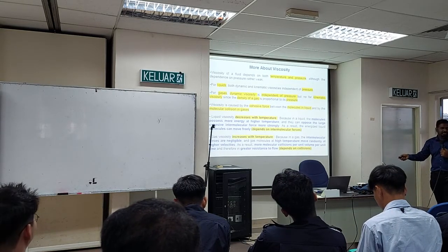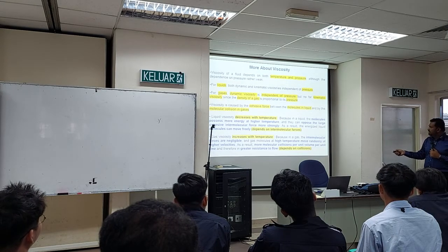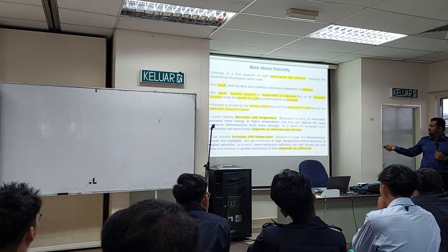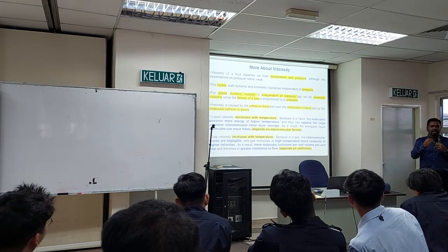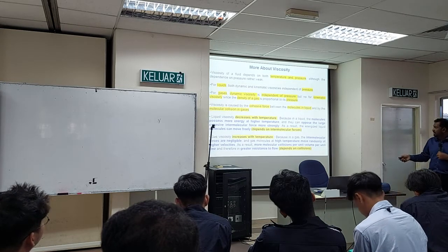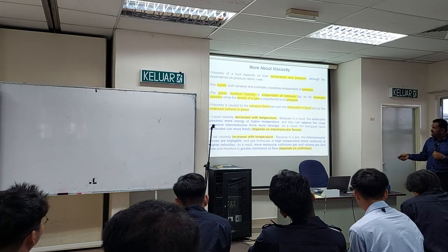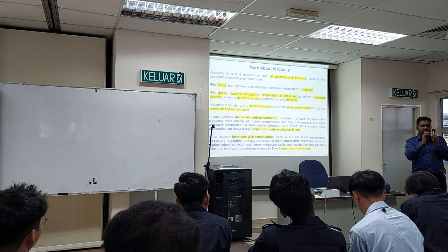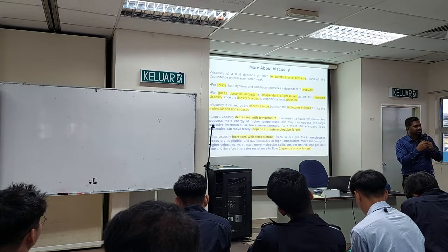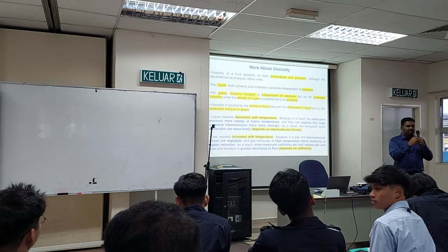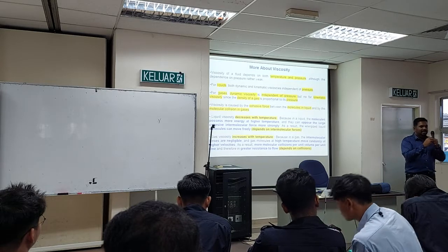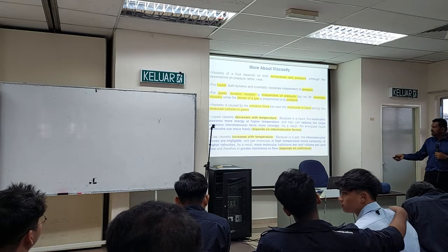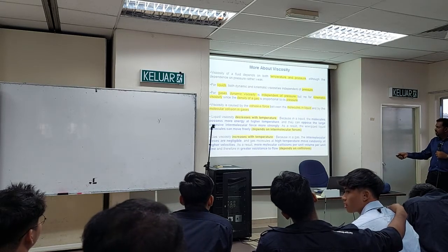Why does the viscosity of the liquid decrease? Because the molecules possess more energy at higher temperature. So if the temperature is high, the molecules move more. Okay, and they can oppose the large cohesive intermolecular force more strongly. So meaning between the molecules there is intermolecular force, right? Okay, the attraction between molecules. So with temperature, it will break the intermolecular force. Okay, so meaning it will oppose a larger cohesive intermolecular force more strongly.